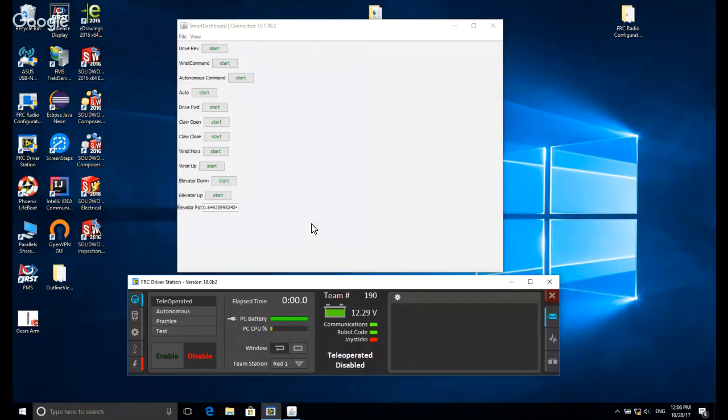It's oscillating. So you can get rid of the oscillations with something called the derivative value, the D value, which all it does is slow this down so you smoothly end at your set point, which is somewhere over here. When you do P and D, you get something that looks like this.